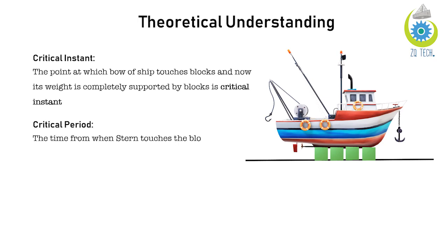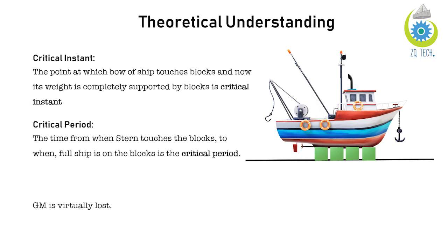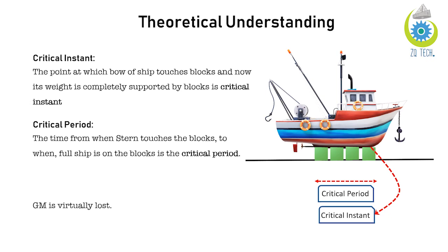So now discuss the points. Critical instant, the point at which the bow of the ship touches the block and now its weight is completely supported by the blocks, is the critical instant. So in the picture you can see the critical instant point.